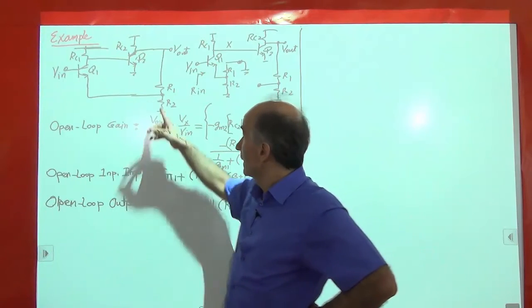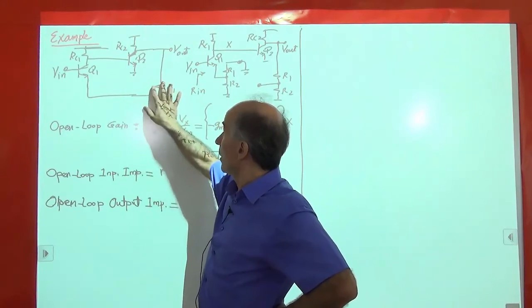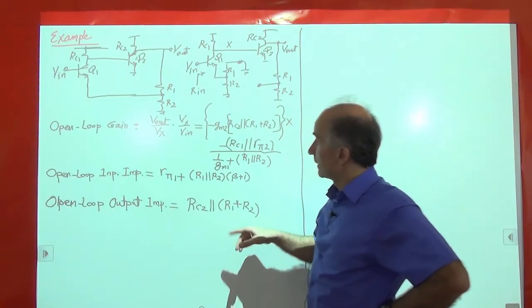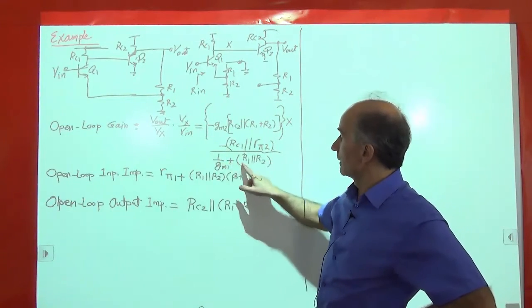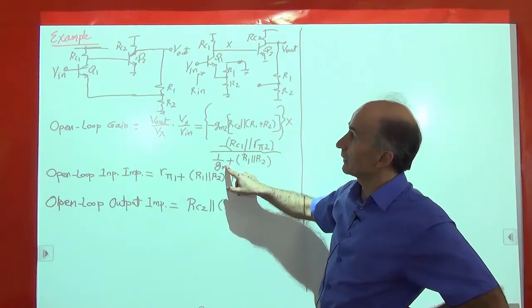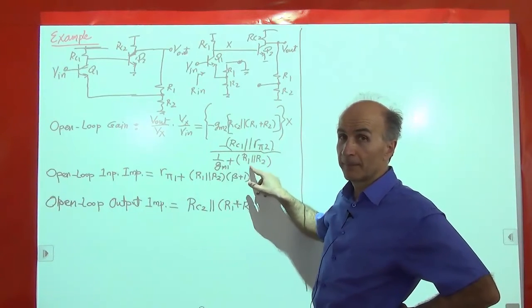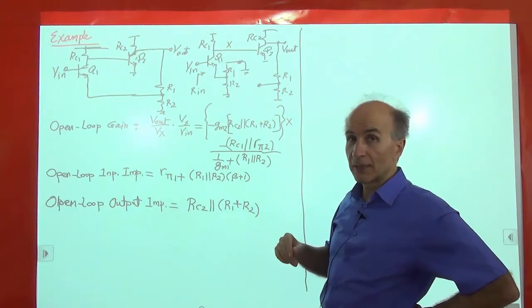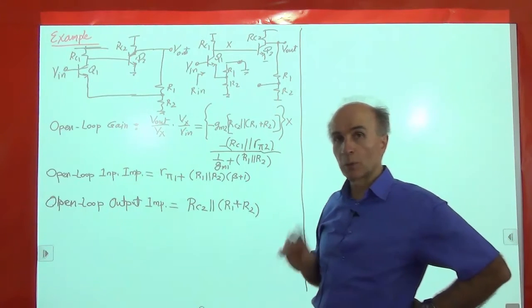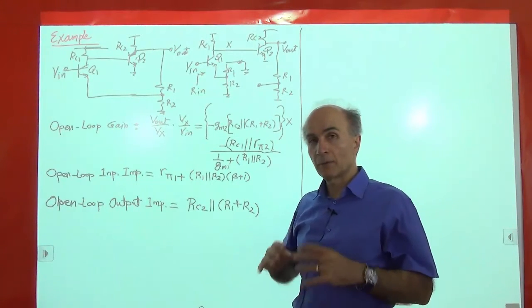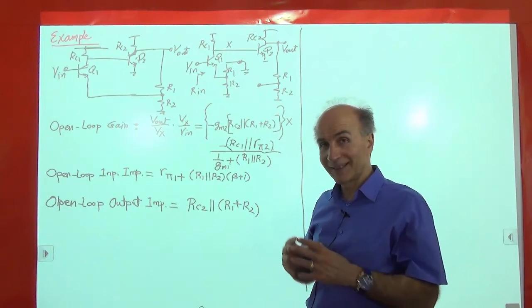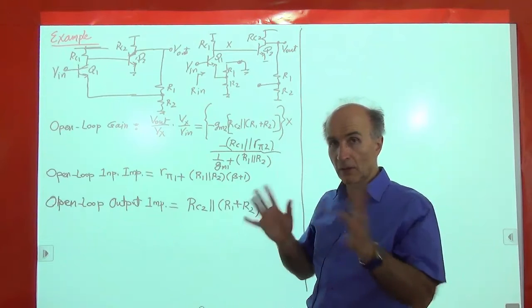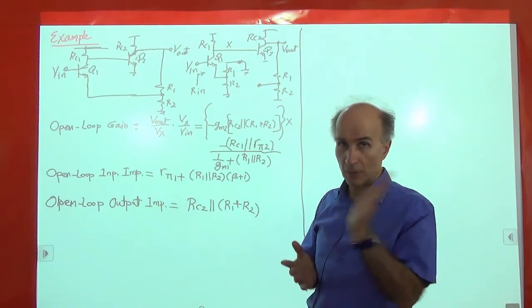The fact that there is some loading upon the circuit by the circuit is already included in the open loop gain. You see here, because we said that Q1 was degenerated. So it's already included there. So actually, we don't need to include it again. But anyway, we will also prescribe 4 methods of calculating K for the 4 feedback topologies, including all the loading effects. All right, so we'll get there later.